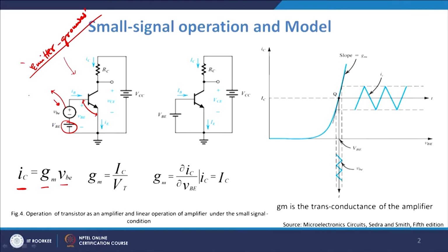One time it is 1 volt, 2 volt, 3 volt, then again comes to 2, 1, and so forth. So, it is rising and falling, maybe a sine wave, maybe a pulse waveform, maybe any of the waveforms available to you. This base to emitter voltage which you give converts into a corresponding current on the collector side, by mathematically multiplying with a value which is gm.